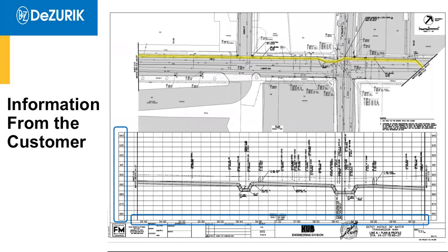And then on the left-hand side is elevation. Now, in this case, it shows elevation in terms of from sea level. It could be elevation from any reference point. It doesn't really matter. It could start at 0 and go some number up or down from there. But in this case, they said elevation started at 860 feet above sea level. And actually, honestly, the pipeline started at about 895-ish feet above sea level, if you look on the left end of the pipe. And you can see that it slopes downhill throughout the distance of the pipe.